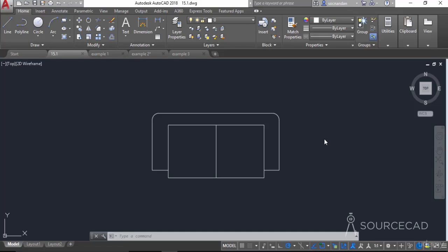So let's get started with the dynamic block tool of AutoCAD. Dynamic blocks are a more advanced type of block in which you can change their shape, size and geometries using a set of rules or parameters, even after inserting those block references in your drawing. As an example, I'll show you some dynamic blocks first, which we will make in this module.